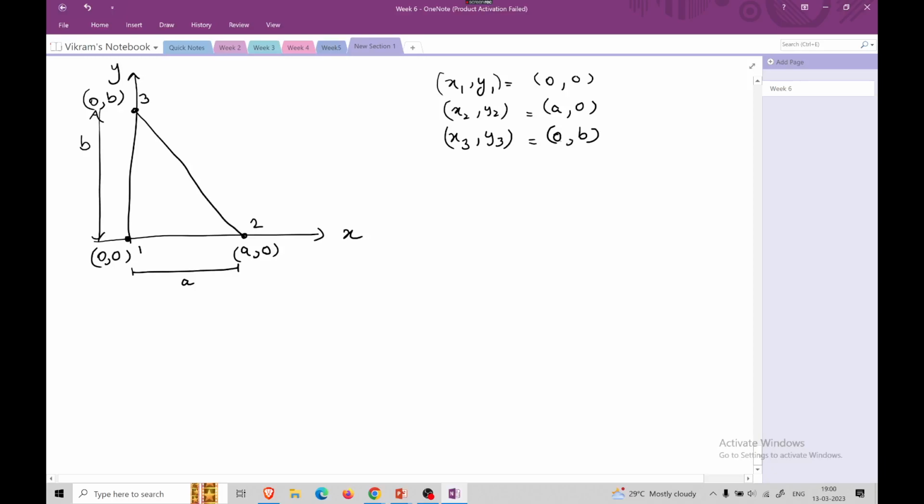So in the previous questions we already derived the shape functions. So I'll simply write what the shape function is. So 1 by 2 times the area of the triangle. So area is nothing but half into base into height, or else you can simply do the determinant also and find out, but you will find that it will be equal to half into base into height. So we already know, 1 by 2A into alpha I plus beta I x plus gamma I y. So alpha, beta, gamma, we have already seen the formulas in the previous question.